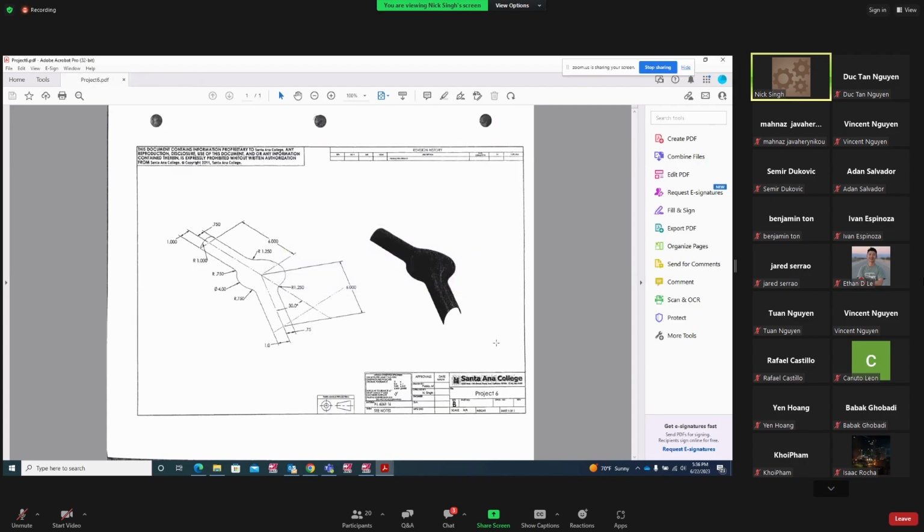Okay, so for your project number 6, we're going to go to construction plane top at Z0. We're going to create this arc with diameter 4 inches or radius 2 inches, doesn't matter.